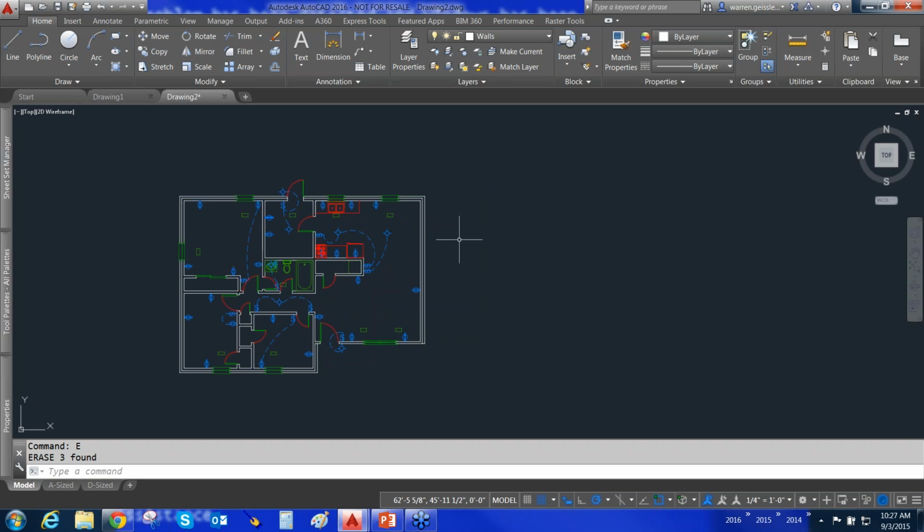There's my first one. Autodesk in this program has incorporated a command called Undefine. This can be put in a Lisp routine. It can be put in your AutoCAD Lisp that loads, or your AutoCAD doc Lisp that loads with every one of your commands. You type in undefine, then you type in the name of the command that you want to undefine, such as, I don't know, erase. And then you will no longer be able to erase anything.